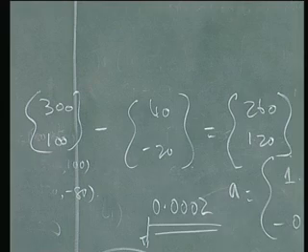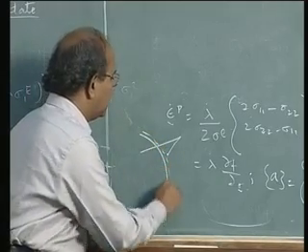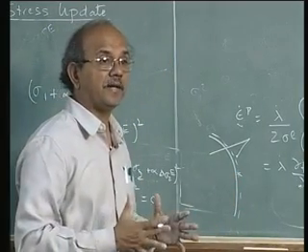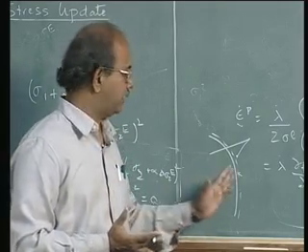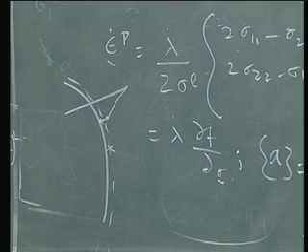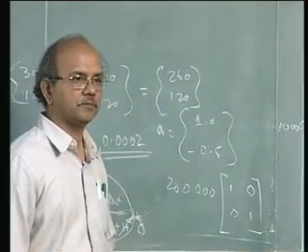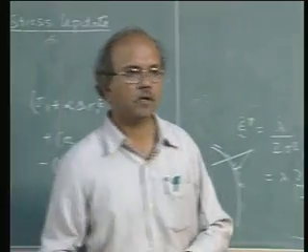And so if I plot the yield surface, after going out, I have come back to that point. But unfortunately, this step of expanding the yield surface is not there because I have not given an h value. So assume that it is at the same point. So what I have to do now is to pull this back onto this yield surface by the correction term which I had given you. So that correction term will take this closer to the yield surface. So this in a nutshell is the complete stress update algorithm.